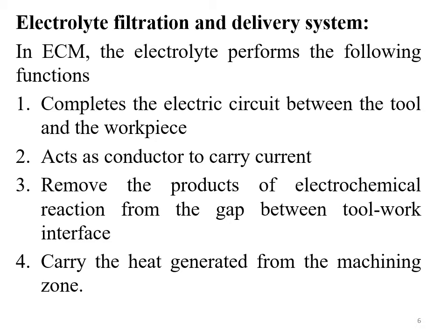During the process, as we have discussed till now, and even in my last video, when the workpiece is being machined with the help of the ECM operation, the metal ions get dissolved into the electrolyte solution. If we keep those metal ions in the electrolyte solution, there are chances that these metal ions may be reduced, and due to the reduction the metal ions may get deposited over the tool.